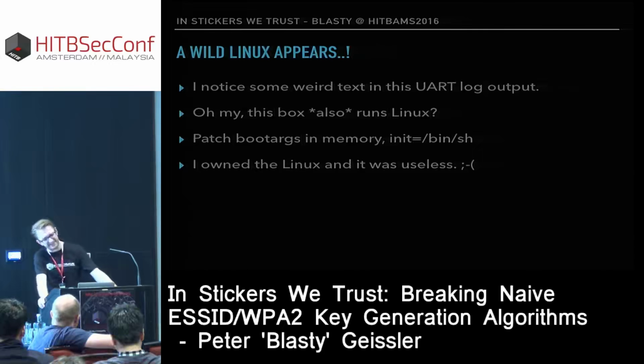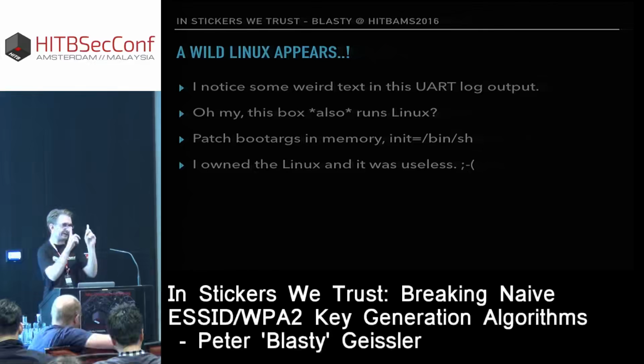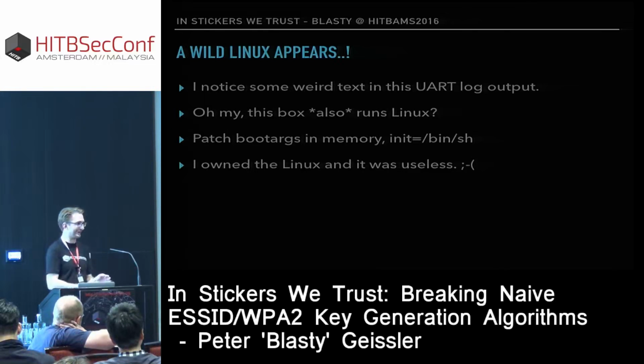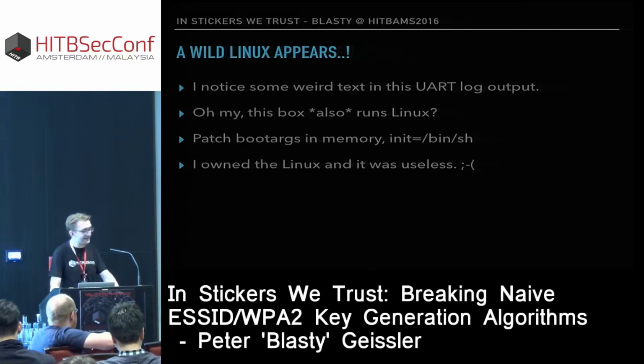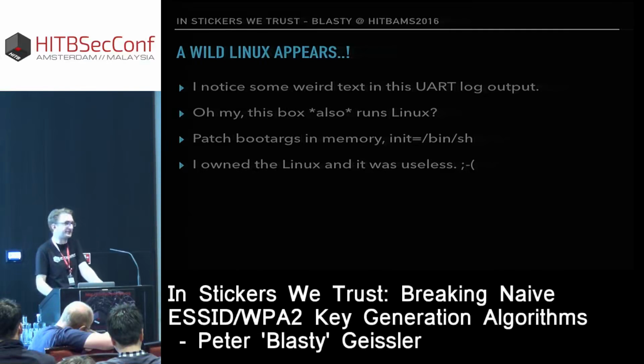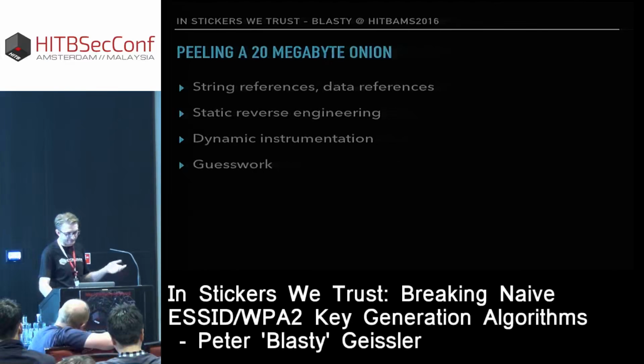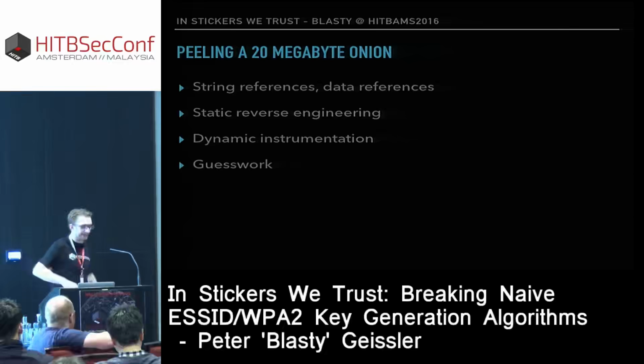So what I did is, the baud rate is also in the boot arguments, and it was set to 115200. But that's pretty long, right? So if you drop the baud rate to 9600, you win a bunch of characters there, and then you remove some other kernel options which you think are not that important or relevant, and then you can append init=/bin/sh, right? So now when you boot the thing with your memory patches in place, you will get dropped into a nice root shell. And then I learned that the networking was broken and the Linux system wasn't set up the way it's supposed to be set up, so it was just useless. It's just sitting there, doing nothing. I wasted all this effort for nothing, right? So we still have the 24 megabyte eCos binary.